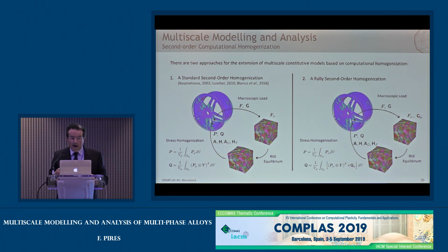A second-order RVE problem is formulated and solved, and then from that solution we will obtain a higher order solution for the first Piola-Kirchhoff stress tensors and the higher order stress tensors, and we are also able to derive the tangents that we require in order to have the system completely linearized, and we can solve it with the Newton-Raphson method. So this is the setting.